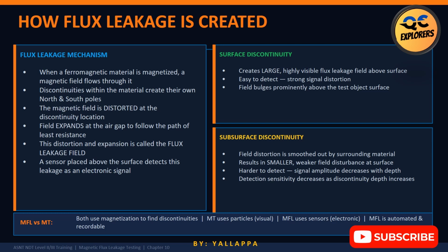Think carefully. A surface crack creates strong leakage. A deep internal defect creates weak leakage. Most inspectors know the theory, but very few understand the practical application. In field inspection, shallow corrosion is easier to detect than deep buried flaws. This is why defect depth matters greatly in MFL sensitivity. Next slide will visualize this beautifully.